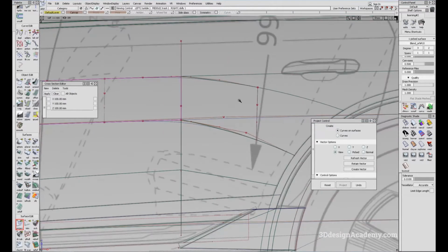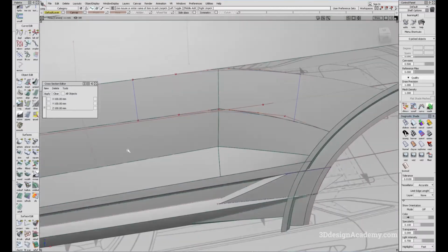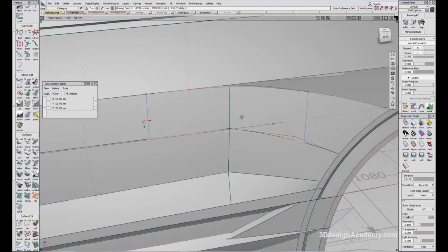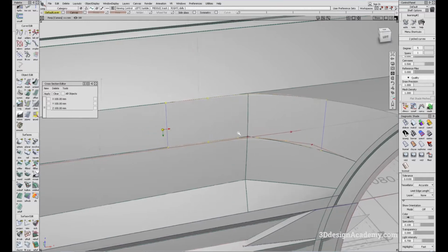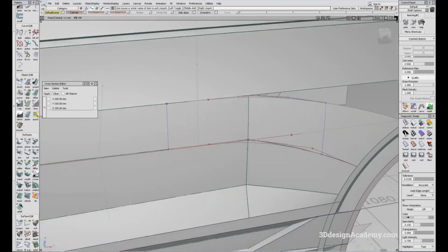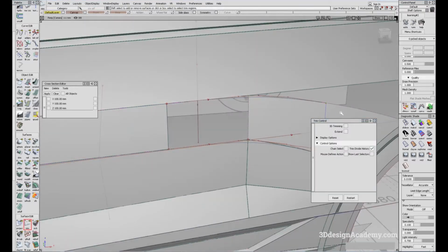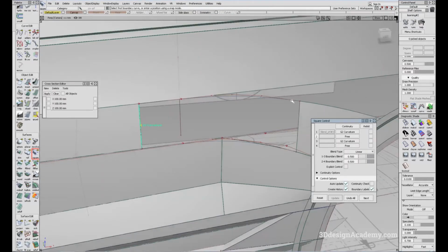So I'm going to project, then delete. Notice that I'm basically recycling the curve that was produced by the surface fillet tool, because it already has basically G2 continuity with lead in, so it's a nice transition. So I'm going to trim over here, and reconstruct it using the square tool. I'm going to say curvature on 1 and curvature on 3. So I'm going to say 1, 2, 3, and 4, like that.